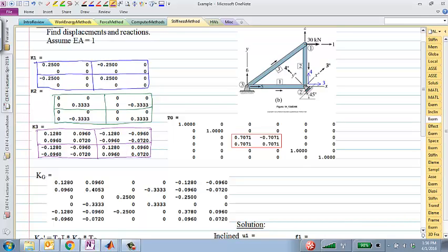And let's see whether this global stiffness matrix that I have on the next line makes sense. Where should this K1 go into the global system? Right, it should be connected to nodes 2 and 3. So that's global degrees of freedom 3, 4, and 5, 6.